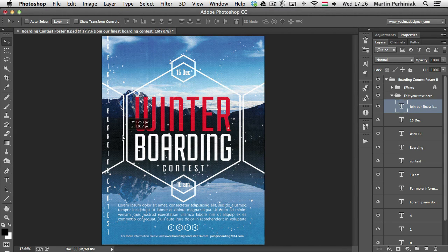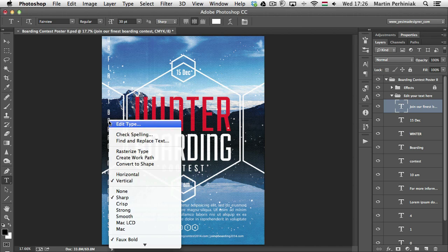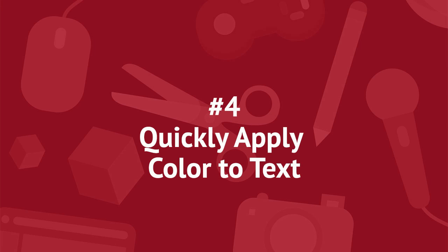So that's also another option which you have, and once again this also works back and forth. So again, I can click on it and by using the type tool, right click, and I can switch back to horizontal. So both of these are completely non-destructive, both having type set into point or paragraph type, and the horizontal vertical option is something that you can easily update later on.